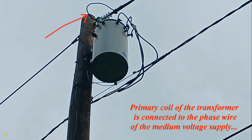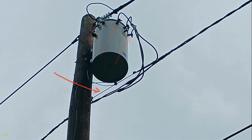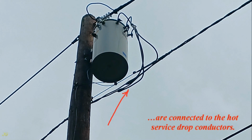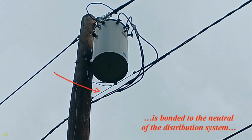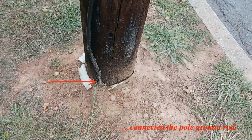The primary coil of the transformer is connected to the phase wire of the medium voltage supply and to the neutral wire of the distribution system. The 2 hot ends of the secondary coil are connected to the hot service drop conductors. The center of the secondary coil of the transformer is bonded to the neutral of the distribution system and to the conductor connected to the pole ground rod.